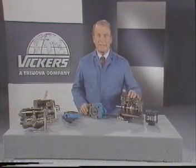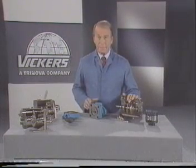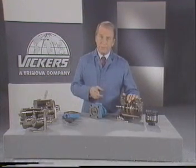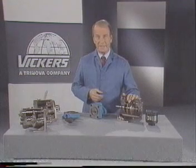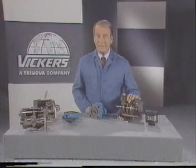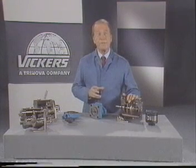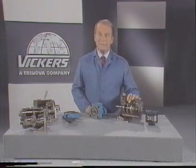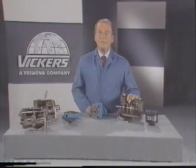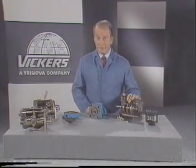These cartridges, incidentally, are available as pre-tested replacement units to speed pump overhaul and reduce downtime in the field. They're usually assembled for right hand, but can be reversed by reversing the ring, rotor, and vanes. The cartridge is accessible after removing the back cover, which in this case contains the pump inlet port. It may be necessary to grasp the cartridge firmly and give it a slight twist as you pull it out of the body. An O-ring seal and backup ring around the hub of the pressure plate prevent leakage into the shaft seal area, but also resist removal of the cartridge.